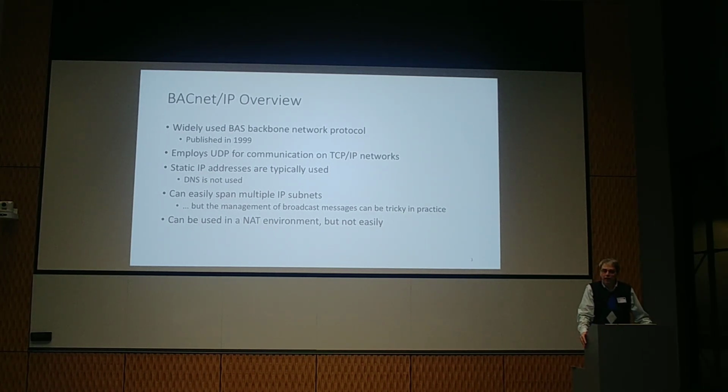BBMDs are a good idea, but they're tricky to apply in practice. We didn't imagine all the ways that they could be misapplied when we designed them. We might have done a few things differently, but we are where we are. And of course, NAT. We really weren't thinking about network address translation when we designed BACnet IP, but it's pretty common today. And although we figured out how to make BACnet IP work in a NAT environment, it's even harder to set up than BBMDs, so it's not something that we ever recommend that anyone try to do.